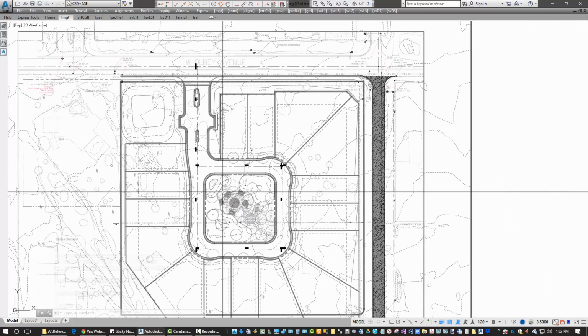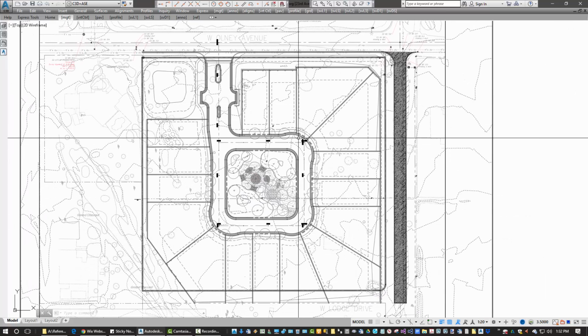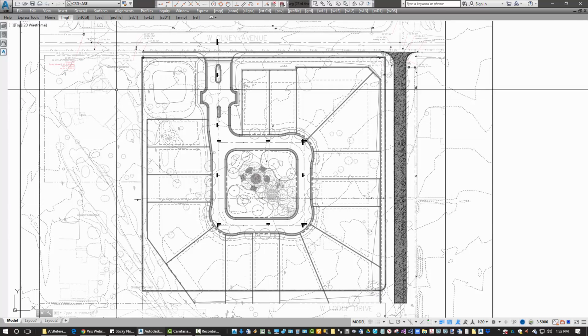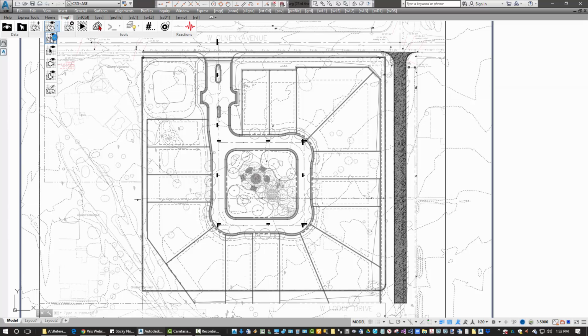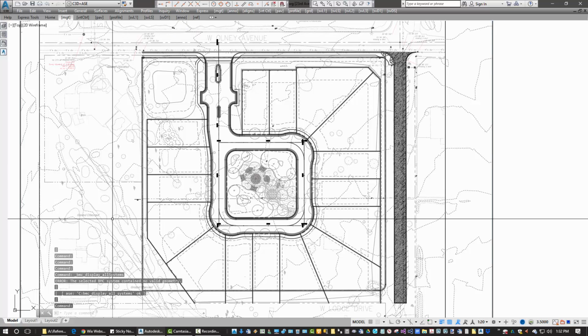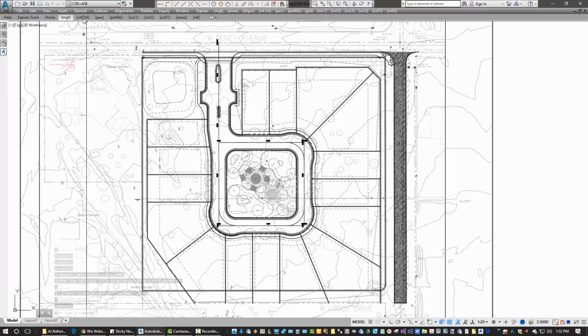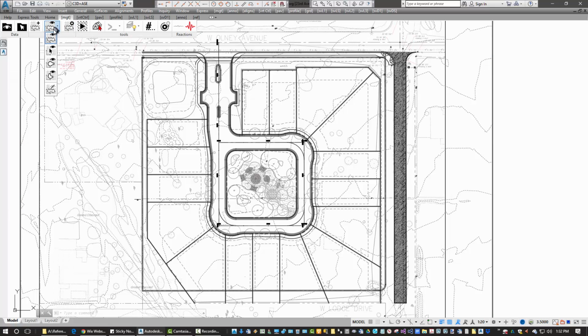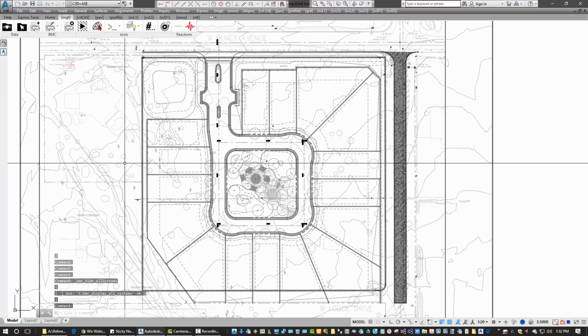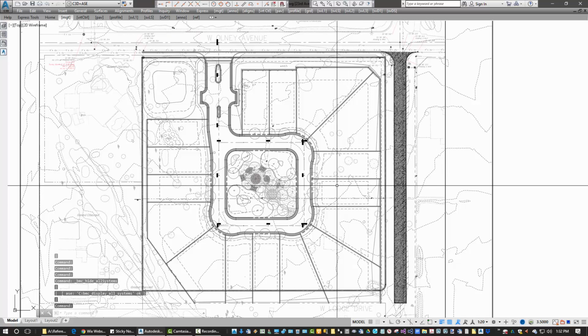We've got existing contours. We've got base map control, which I can verify also by displaying that. And we've got our alignment. So the next step, let me hide my base map control. The next step would be to set design markers.